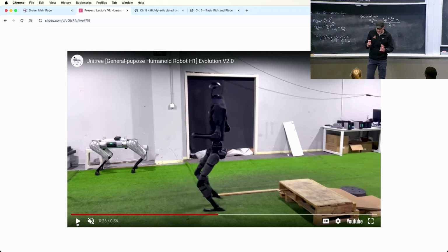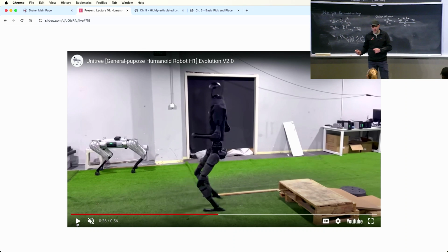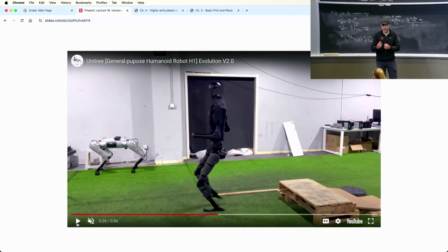Okay. So one of the subtle reasons why I think RL is working well in quadrupeds and in this biped, and maybe not in all the bipeds, for instance, is that when you do have very light legs, like that slip model, and your feet are smaller, then your sim to real gap is smaller because your impacts with the ground are less severe and they don't need to be modeled as carefully, right? And certainly point feet are easy to model in simulation. So I think one absolutely could do the work to make, let's say, Optimus in simulation sufficiently accurate to do RL in simulation. But I think it's easier to do it on these really light-footed robots.